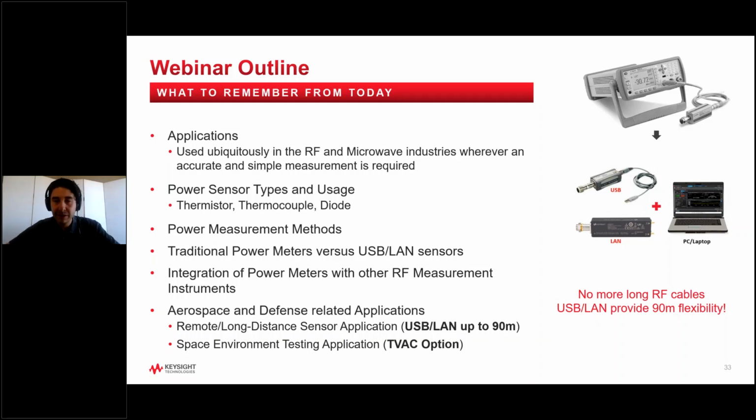Power measurement methods, we talked about our traditional power meter, power sensor. Well, we can now port over and really leverage the BenchVue platform using a computer to connect your devices through USB or LAN. Or perhaps you're using a Keysight piece of test equipment already, like a network analyzer or a signal analyzer. Those will also interface well with your USB or LAN sensors.